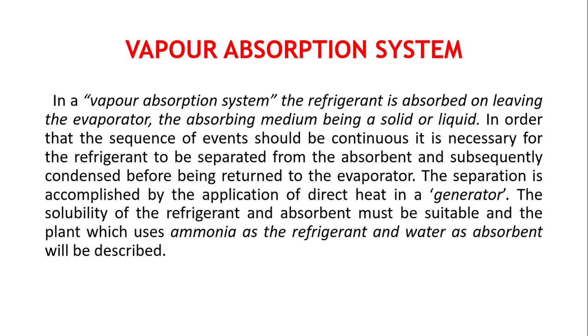In the vapor compression refrigeration system, the refrigerant is compressed in a compressor and sent as a high pressure liquid, which is circulated in the evaporator, where the space to be cooled is. The refrigerant absorbs the heat and is again converted to gas. It is passed again into the compressor, where it is compressed to high pressure. This cycle repeats in the vapor compression refrigeration system, but the main difference between the vapor compression and vapor absorption systems is